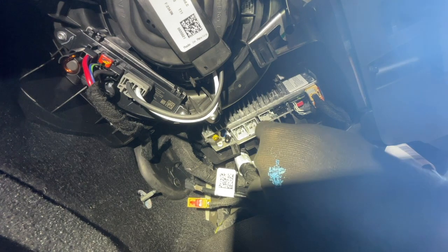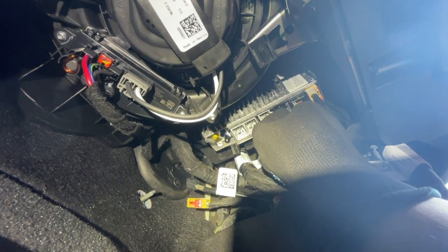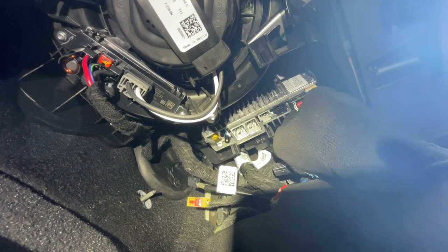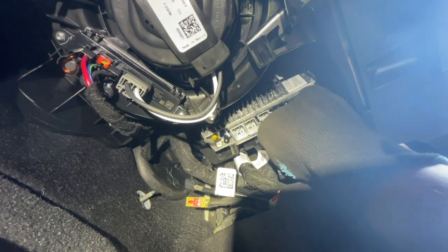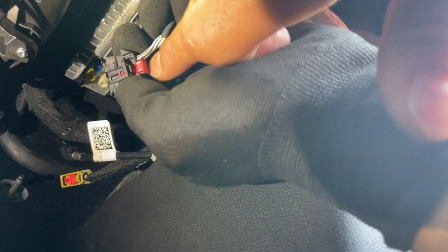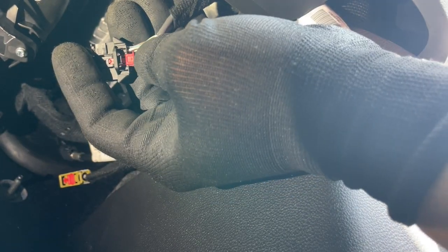Just like that. We have this black connector here on the far right, and this one also has a red TPA. You want to pull down away from the module. So this connector gave me some trouble. I couldn't get it on camera on how to remove it, but I got it out. And so on this one here, you're going to again release the CPA by bringing it down, and then the release button is actually right in front of it. So you want to press that and release. This was rotated in this orientation, so I couldn't do that and get it on camera, but slide the red TPA down and then push in right in here to release.